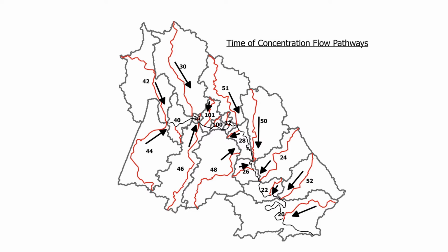Time of concentration must be calculated in order to do rainfall runoff modeling using the unit hydrograph method of transforming runoff into stream flows. GIS was definitely helpful in this case. It helped me get accurate flow path lengths and elevations at the beginning and end points of the 3 types of reaches for each of the subbasins.